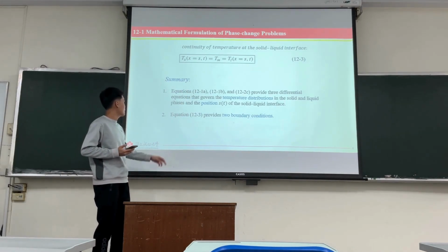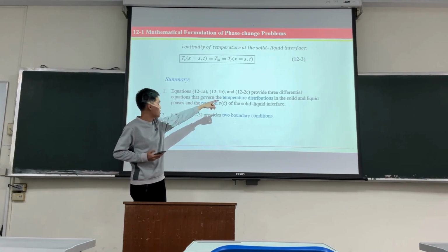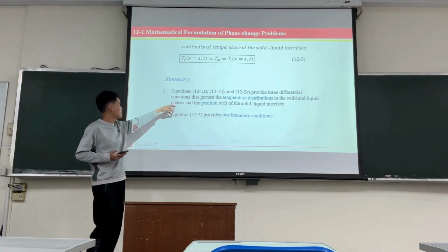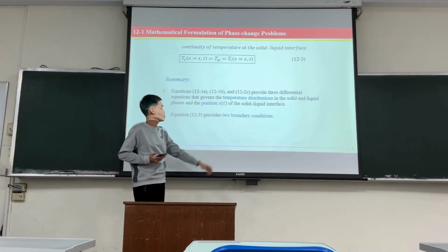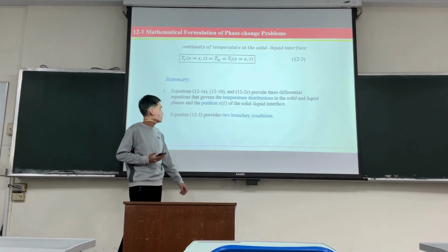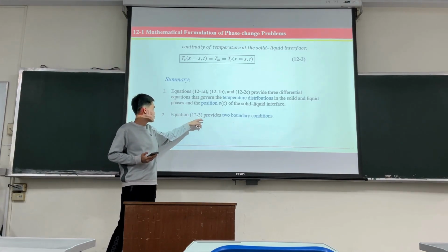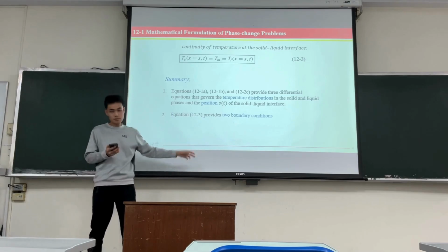In summary, equations 12-1a, 12-1b, and 12-1c provide three differential equations that define the temperature distribution in the solid and liquid phase and the location s(t) of the solid to liquid interface. And equation 12-3 provides two boundary conditions.